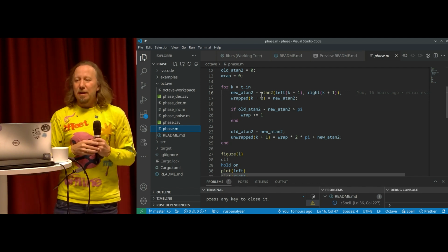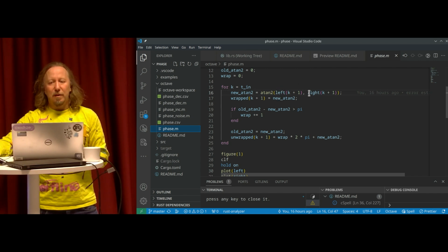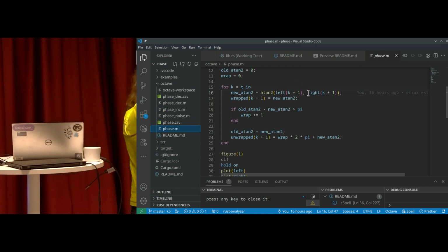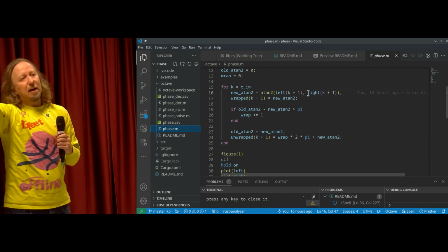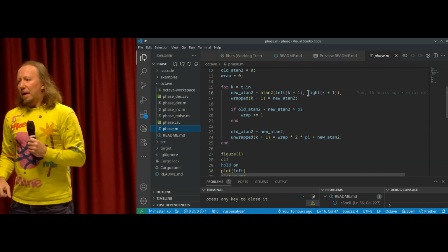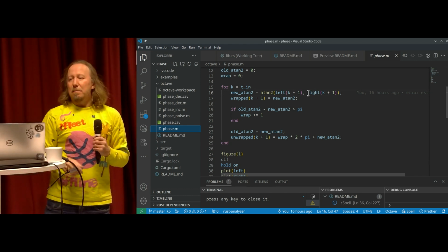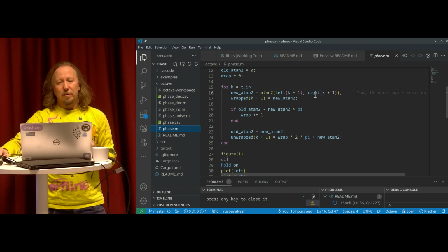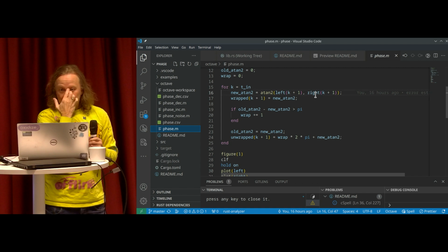So you can get a phase value out of the two left and right signals. Essentially, it says how far in you are on a sinus signal like this, and by having two of them, you can discriminate in a much better way. So that's why we have left and right. That also allows us to track the direction, as we'll see later.